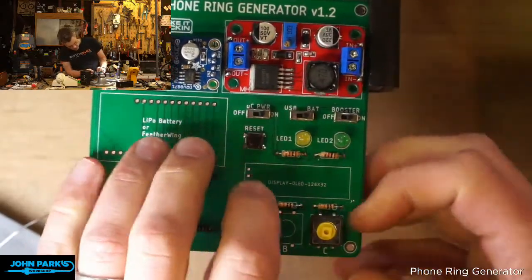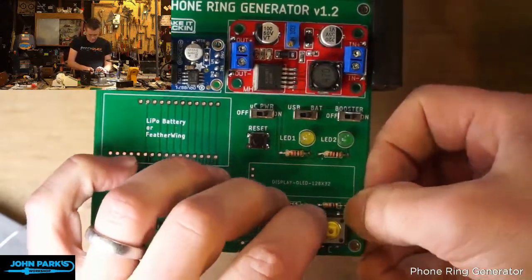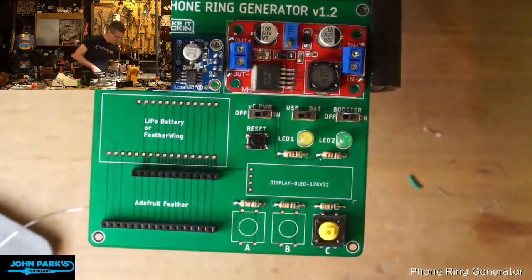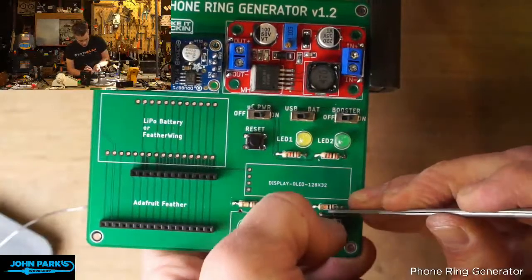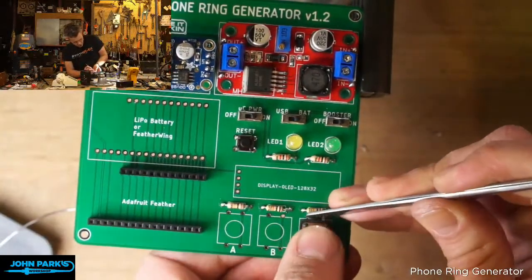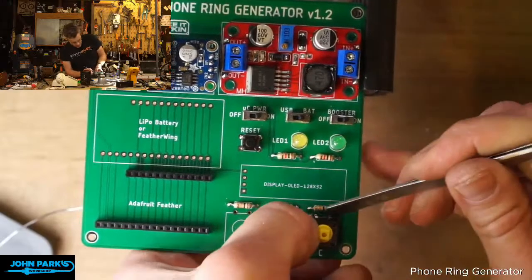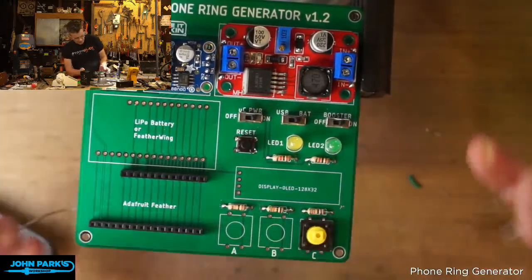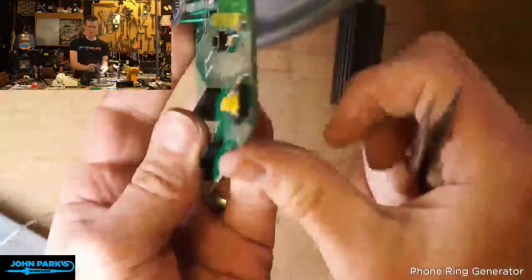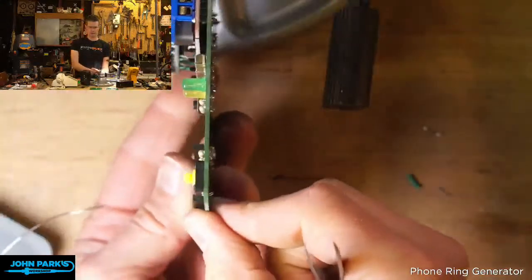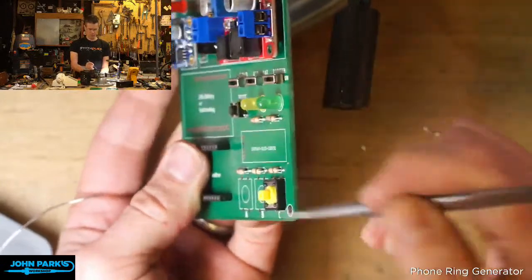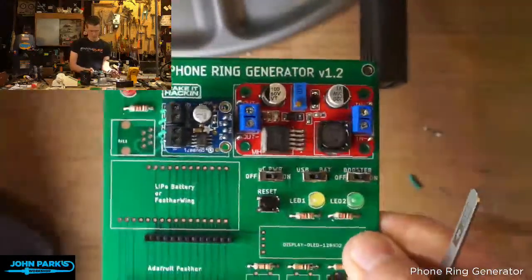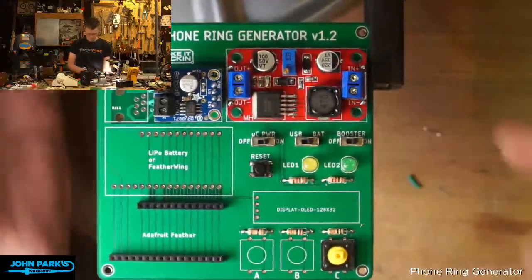Okay, so these ones, you can usually just kind of manhandle them, but if you want to avoid bending, get a little flathead screwdriver, or in this case I'll just use the back end of these tweezers. I'm going to give those legs a little push inward as I press this down, and that helps get it seated really neatly there. You can see these legs have a little bend to them to grip the board when they go in properly. You just want to be deliberate with those.